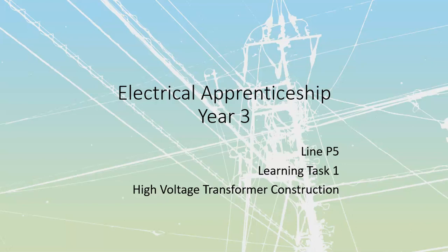The purpose of transformers is generally to change our values of voltage and current. We'd like to bump up our value of voltage, which drops our value of current, so we can increase our transmission distance while not having as much losses on the system, I squared R losses, nor as much volt drop on the system, IR drop. So we like to take our medium values of voltage, increase them to really high values of voltage, transmit them across the province, and then drop them back down again.